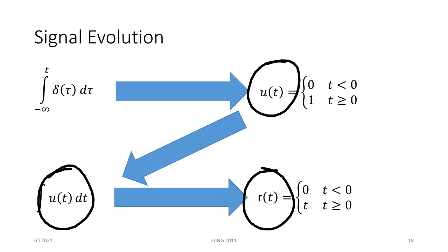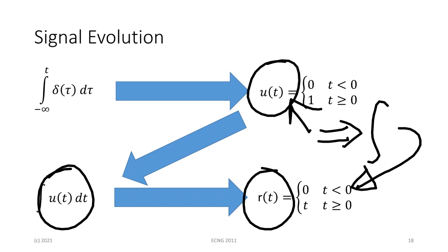You can start off, this one is right in the middle. So we were talking about generating these things in practical terms. If I have a unit step now, and I pass the unit step through an op-amp integrator, I can create a ramp. If I pass it through an op-amp differentiator, I will get an approximation of an impulse, because of course it can't get infinite height.